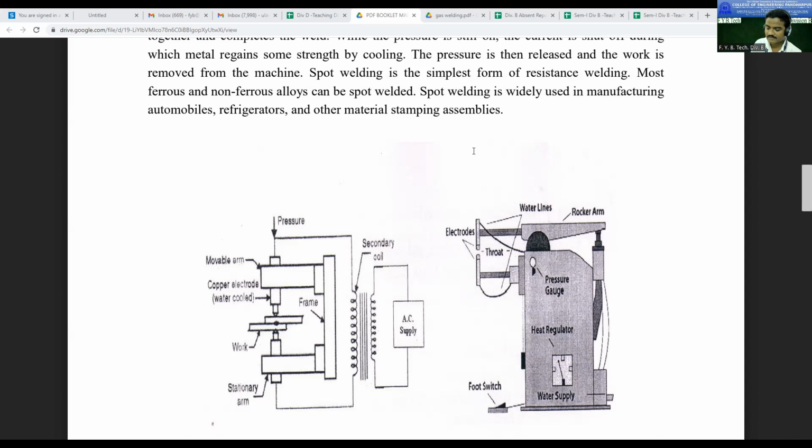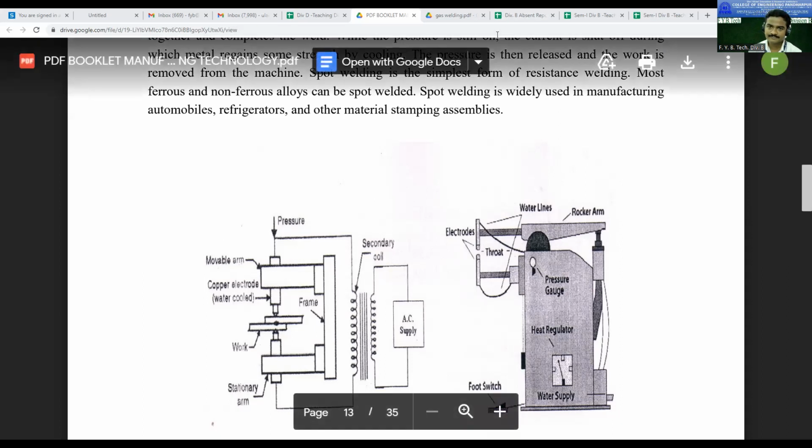Spot welding can be performed without any special skill. Joining different metals. Okay. Spot welding can be preferred for joining different metals. So this is one advantage we can write down. अजून काय सांगताय?